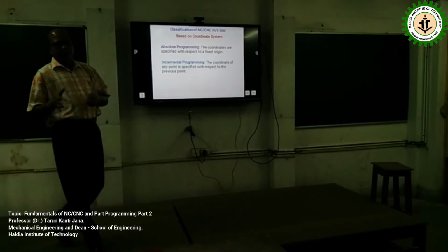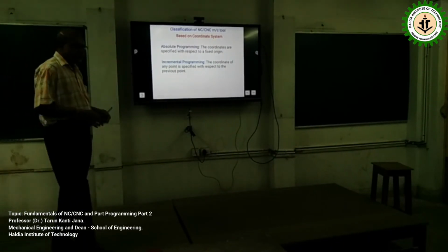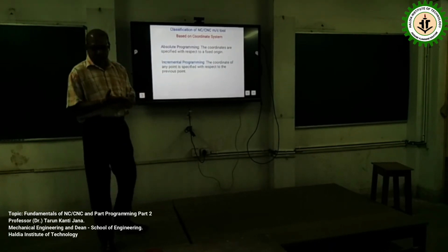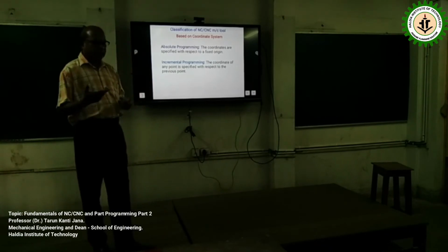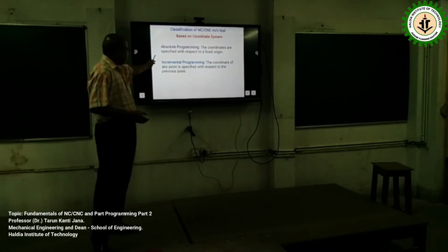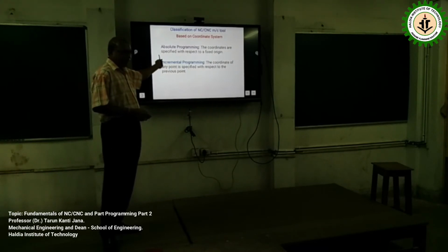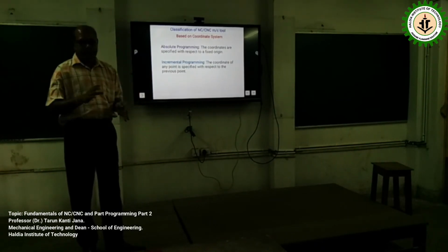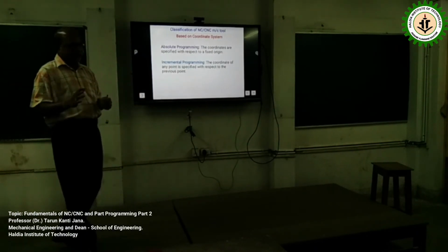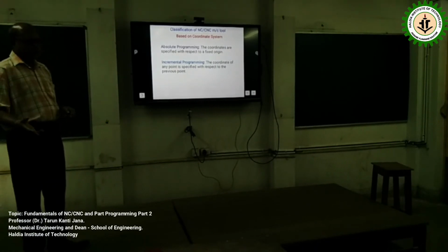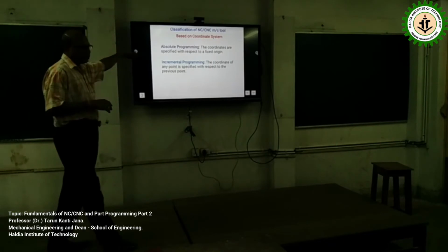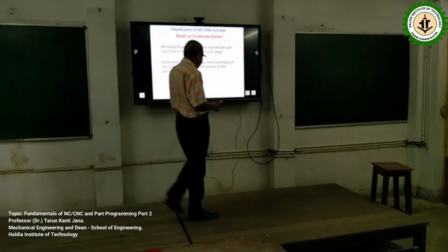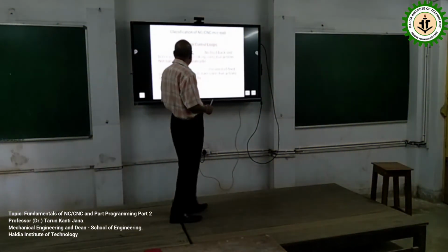Depending on the drawing dimensions of the mechanical components, sometimes this may be useful, sometimes that one may be useful. It is the wish or the prerogative of the user or the programmer. He can choose either with the appropriate G codes, and he can even toggle. It is not that once you have started writing the program in absolute mode, you cannot switch over to incremental. There is no such restriction. With a program code you switch to incremental, and again you can come back. So at any number of times you can toggle between these different approaches to the program.